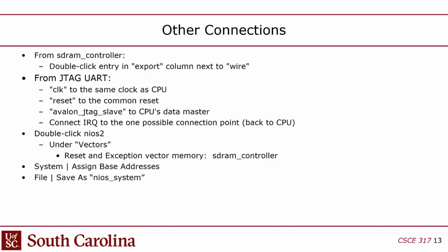Now with the Arduino, on the other hand, we actually had UART. There were two physical wires that we would run into. Well, actually, though, we still went over USB at some point. We had to go UART to USB. I don't remember how we did that now. We had an adapter.